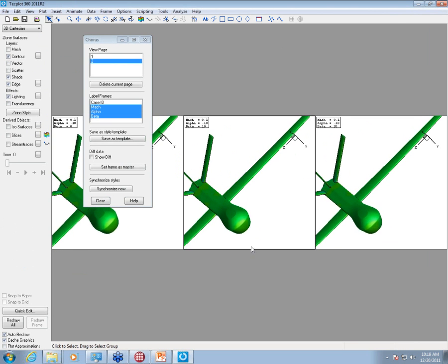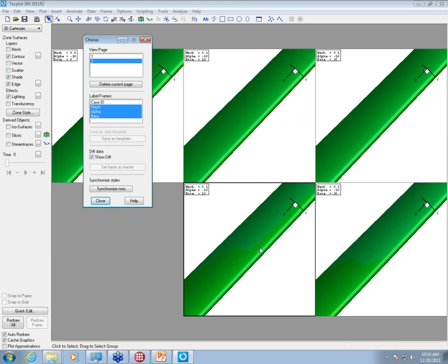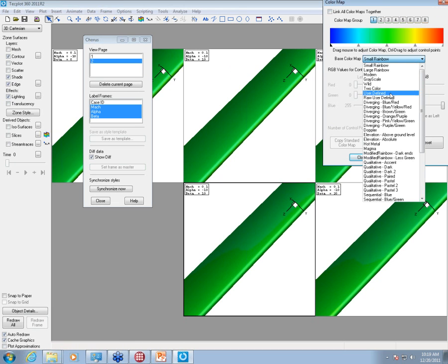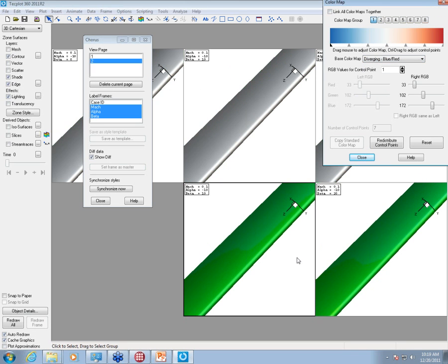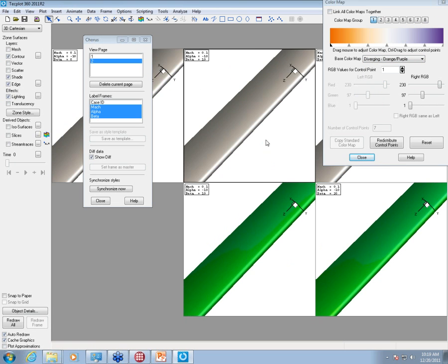And then if I'm really interested in the delta P right here on the leading edge, I can grab, say, the base case, which would probably be, let's use this one at beta 0. And I'm going to do a quick difference. And now what we're going to look at is a quantified difference between these. Now you can see it's not that different. I'll change the color map to make this a little easier to see. So by using, say, a color map that's like the divergent red-blue, actually make sure we're looking in the right area. How about, there you go, I still can't see very well the difference.